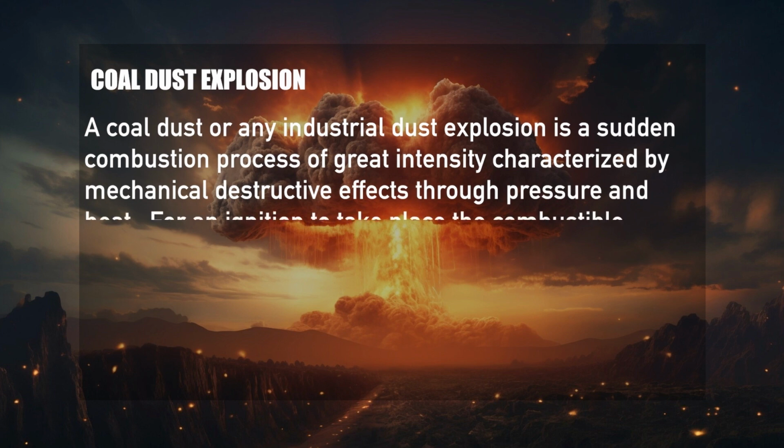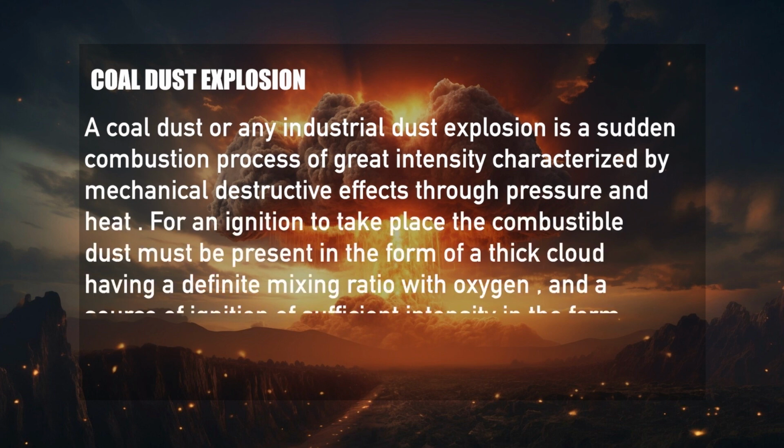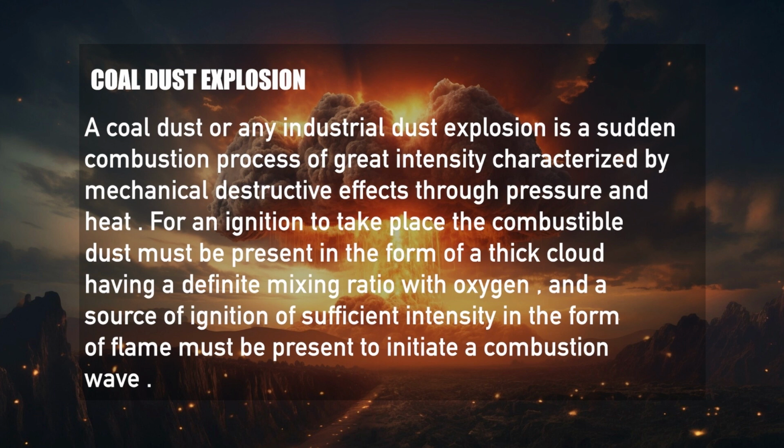Coal dust or any industrial dust explosion is a sudden combustion process of great intensity, characterized by mechanical destructive effects through pressure and heat. For an ignition to take place, the combustible dust must be present in the form of a thick cloud having a definite mixing ratio with oxygen, and a source of ignition of sufficient intensity in the form of flame must be present to initiate a combustion wave.